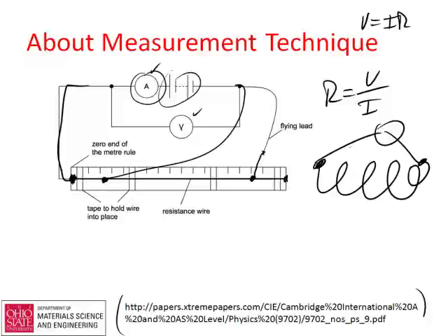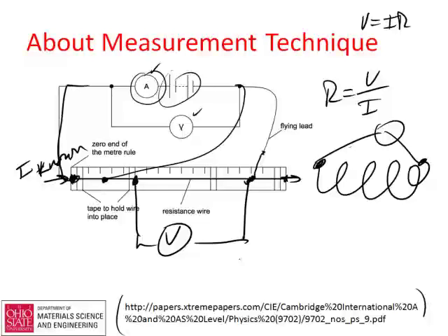So the other thing you can do is put a known current through here, and if you have some contact resistance, you could do that, and then just measure the voltage across any 2 points on this. If you know the distance between those 2 points, you know what I is because you measured that here. You know what the voltage is, so you could figure out the resistivity of the wire in between here. It might be a little complicated. I'm sure if you want to, you'll figure that out.